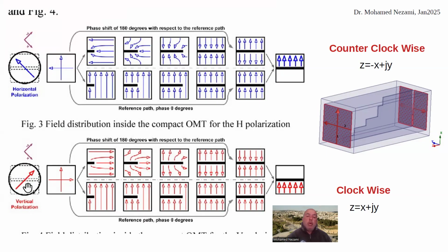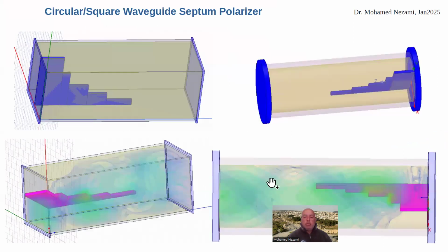If it's the other way around, the signal will get in the other one. And between this, the propagation into the septum from the smallest step to the largest step, which divides the square waveguide completely into two separate rectangular waveguides, you can see what really happens, which is what I just showed. And you can go to many of these microwave books, and of course they detail it.